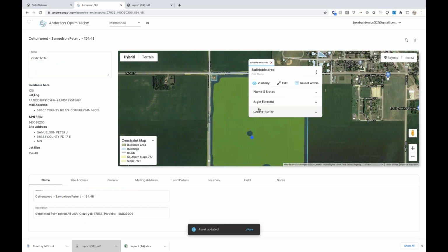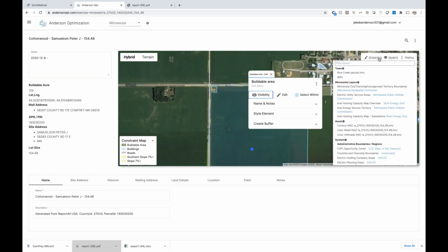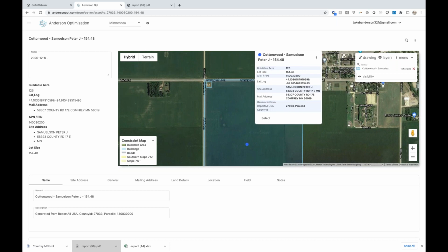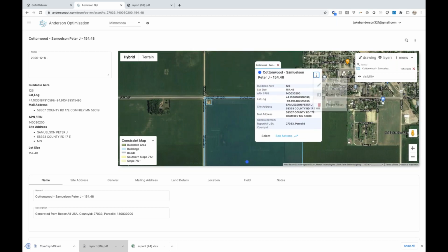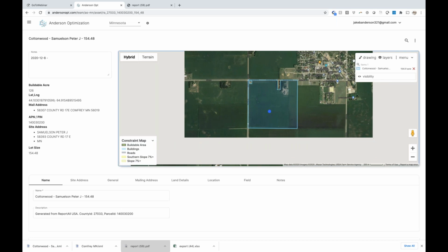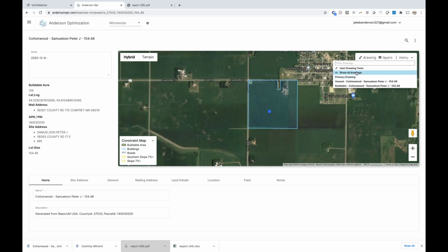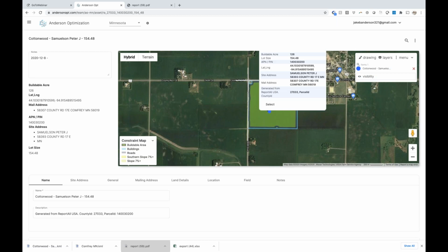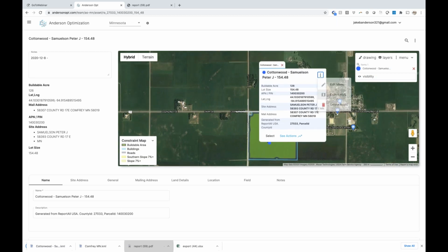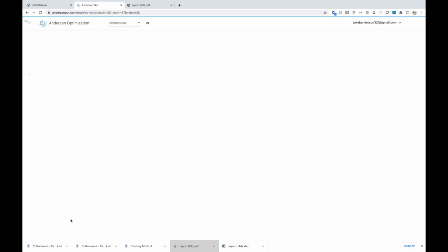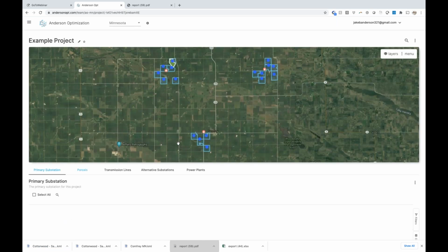And for PlantPredict, what we first need is just our property boundary. So I'm going to just hide all of my constraints. And I'm going to click on this site and hit export KML. And then we also want to make sure that we have the hazards. So then I'm going to do a second export that is going to export my hazards. And once again, I'm going to click and hit export KML. And just for time's sake, I've done this with all three of these parcels that I had left in my project before and pre-passed them over to David.